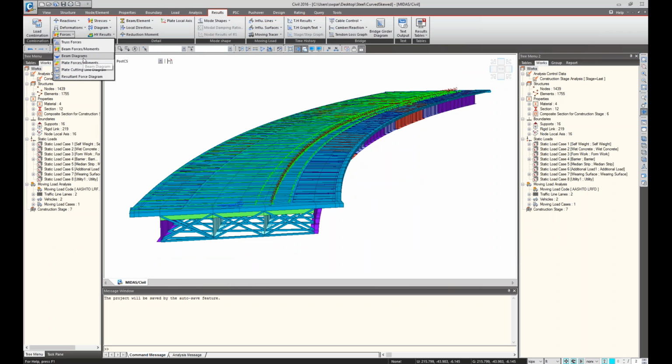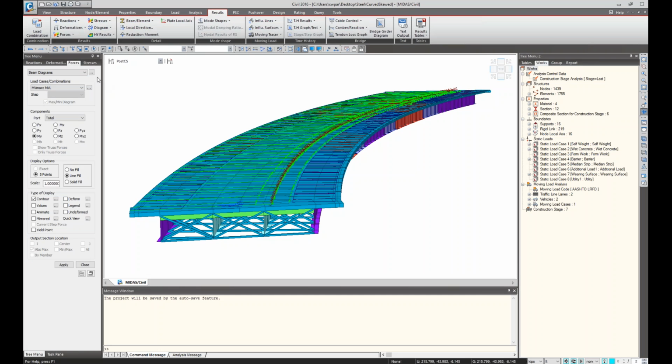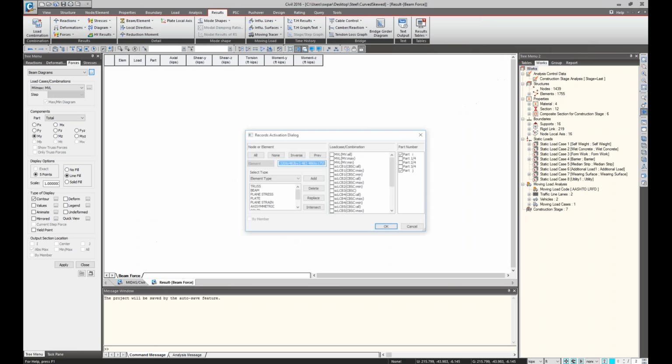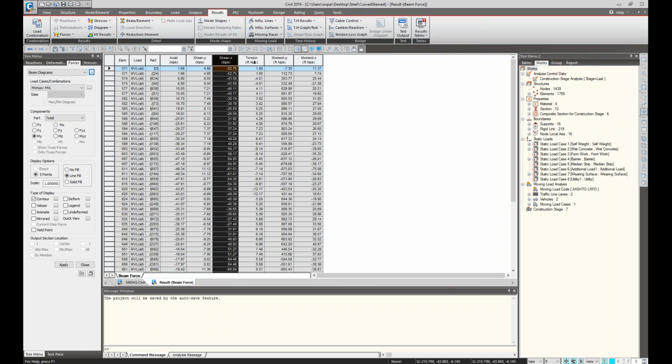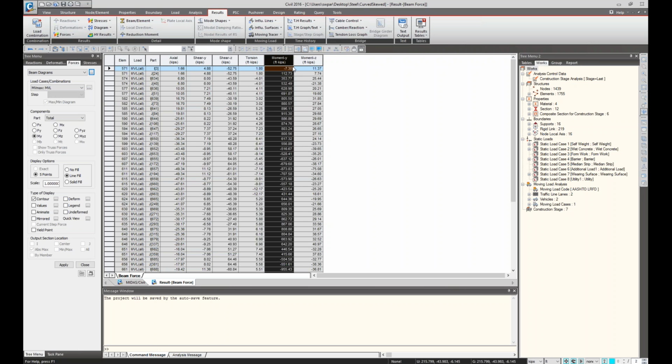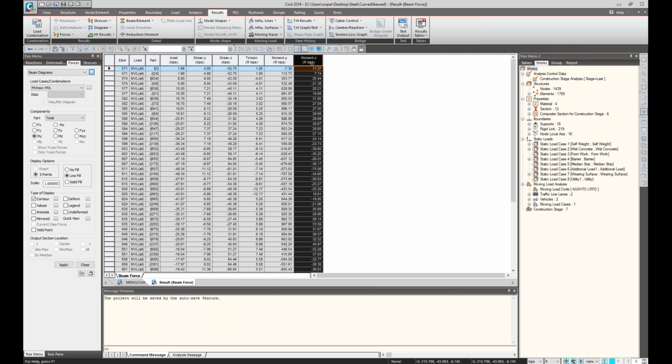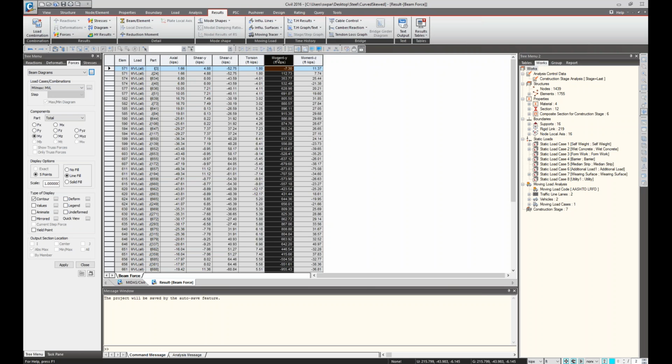And when you go to forces and a beam diagram, I will just create the structure values with the table information and structure groups, and click OK. And you can see shear values, Z values, and moment. This one is for the strong axis, and this one might be the weak axis. Those show you the maximum values, considering all the moving load cases generated in MIDAS Civil.